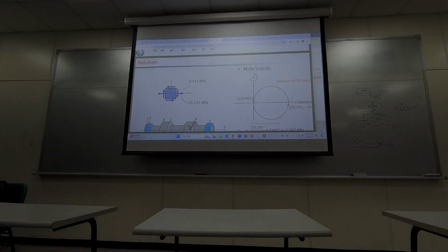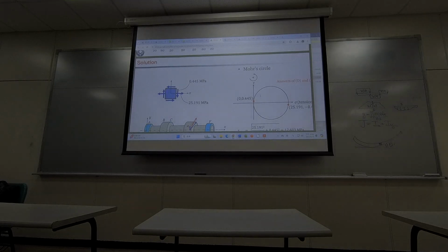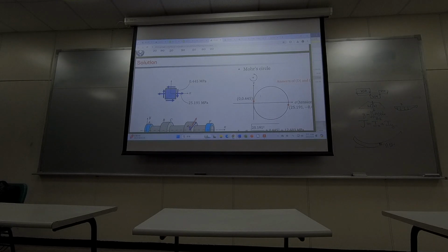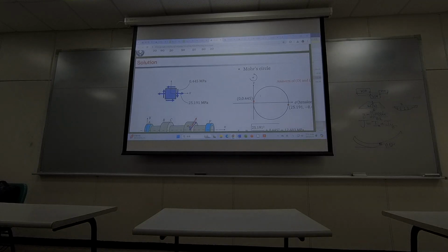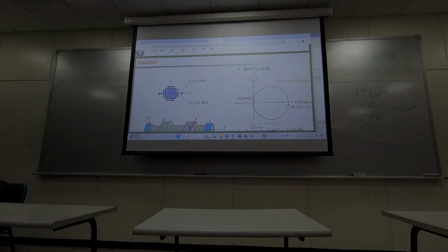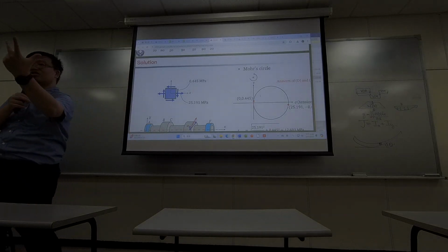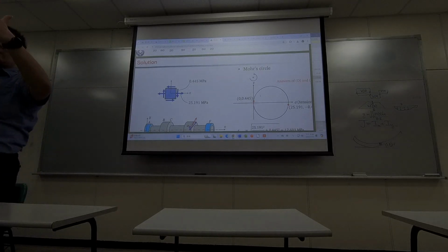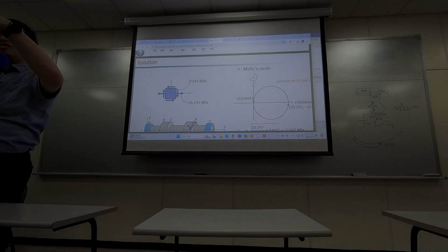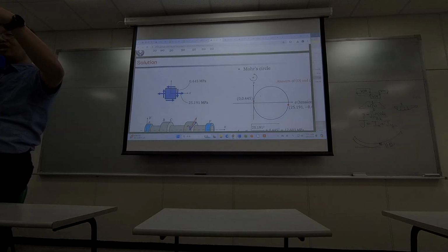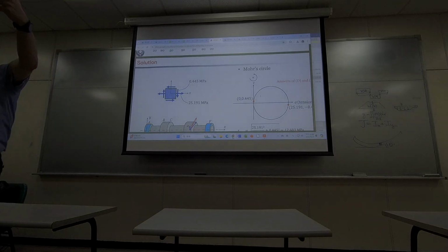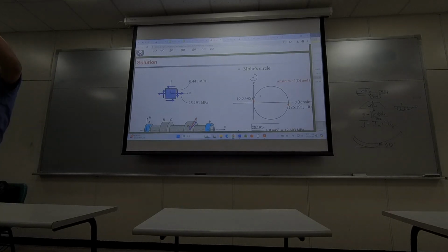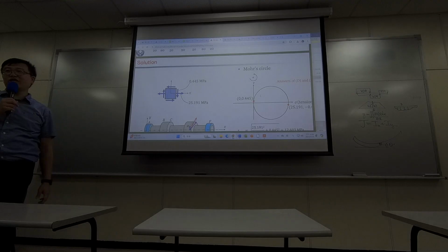Actually, along this observation coordinate, you realize the material is carrying a certain strong load along the rotated coordinate. So the material would fail along that particular coordinate. So the purpose of Mohr circle is to rotate the observer's viewpoint to figure out, okay, along this coordinate, the material carries the strongest load. So from now on, we should study this material along this coordinate, the so-called principal stress coordinate.